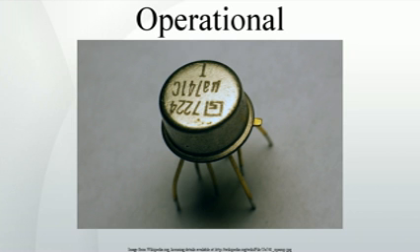Differential amplifier. The biasing circuit of this stage is set by a feedback loop that forces the collector currents of Q10 and Q9 to nearly match. The small difference in these currents provides the drive for the common base of Q3/Q4. Note that the base drive for input transistors Q1/Q2 is the input bias current and must be sourced externally. The summed quiescent currents of Q1/Q3 plus Q2/Q4 is mirrored from Q8 into Q9, where it is summed with the collector current in Q10, the result being applied to the bases of Q3/Q4.